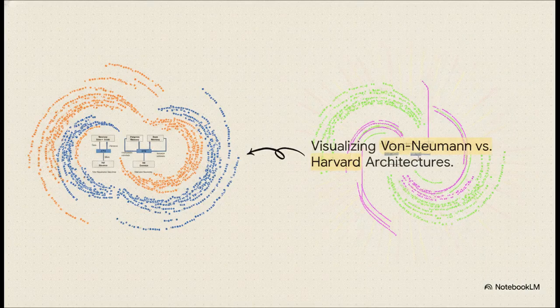And this brilliantly illustrates that highway analogy. When you map out the von Neumann machine, it routes both data and address lines right through one central CPU bottleneck to a combined memory block. But the Harvard machine elegantly splits that flow. Program memory gets its own instruction address pathway, and data memory gets its own totally separate variable address pathway. By separating these pathways, you can theoretically double your memory access throughput. It's a real game changer.